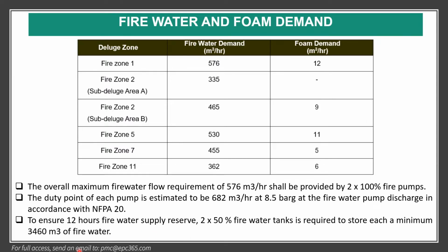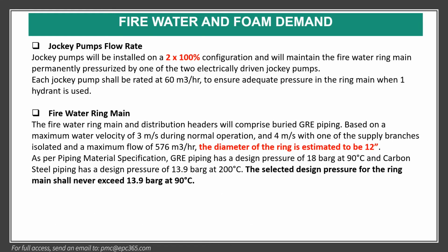So about the fire water tank, certain projects get 6 hours, but you have to be very careful that 12 hours is for the local authority, and the local authority normally asks for 12 hours as far as I know. So if you put 50%, you can calculate the capacity of the fire water tank.